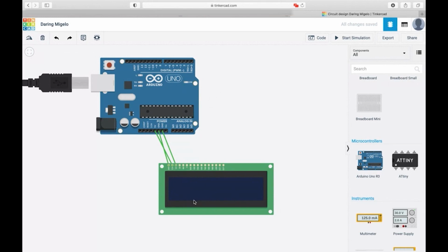So whatever we have to display here, that is where it is stored. A register is an element where we can store n number of bits, it is a part of the memory. This register select we will connect to any of the digital input output pins. You can use any digital input output pin.